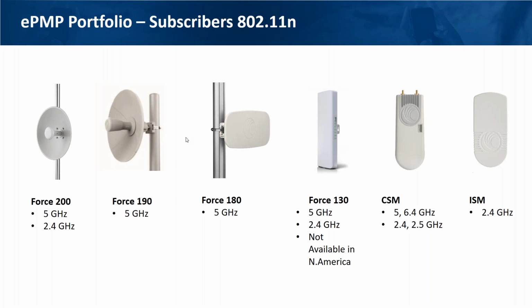So you may get some benefit in a high noise environment. The 3000 has an 11AC Wave 2 air interface, which also has some better coding rates and other benefits, so you may not see as big of a boost as you did with 11N, but you would see some boost. Your mileage will definitely vary depending on the noise floor, the location of those SMs, how they are relative to each other, and how much benefit you get from that beam steering.